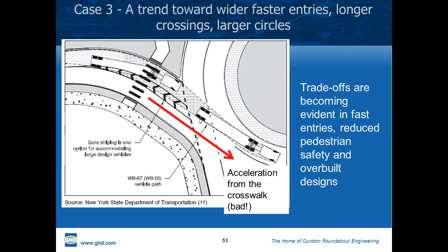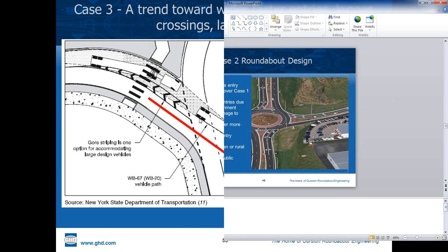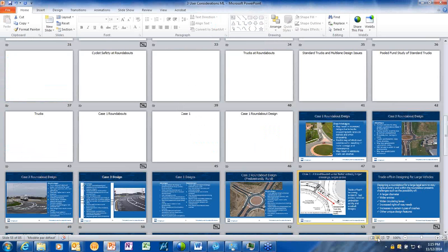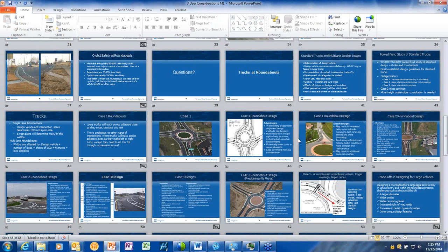Oh, OSOW. I'll stop for questions at that point because there's a lot of material on this truck module, and I'd like to hear some reactions as to what people are doing, what other designers are responding to these needs and interests. I mentioned that it's difficult to judge which case to use. Is it based on 5–10% trucks or the total volume of trucks in the traffic mix? And so no clear definitive guidelines have been developed.